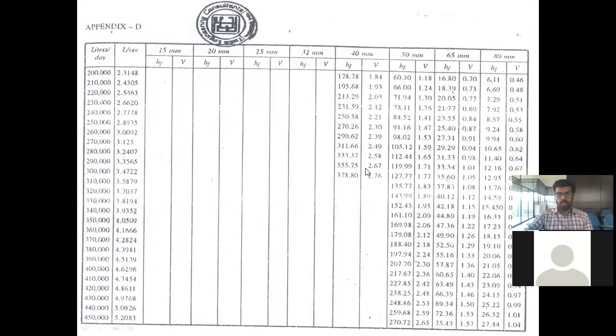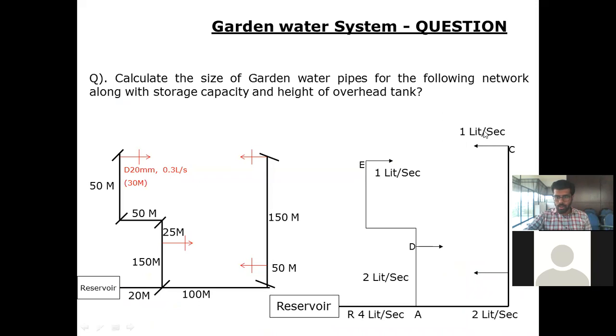So we have already found out the longest length, right? We have already found out the longest length. So this pressure will be compensated because we have already taken the longest length only. So the pressure at this end will be... when we took the longest value and we found out that there will be 2 meter head at the end of this sprinkler, we can blindly say that there will be 2 meter at this short length.